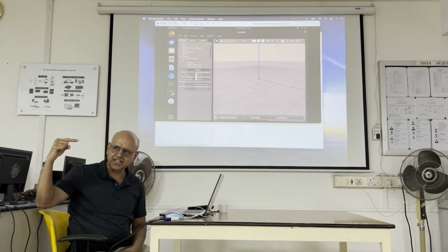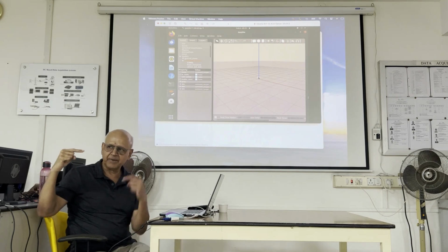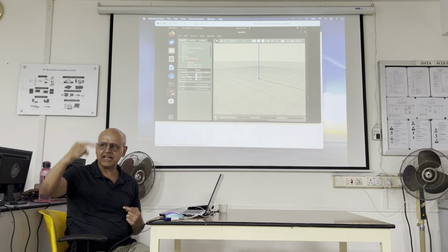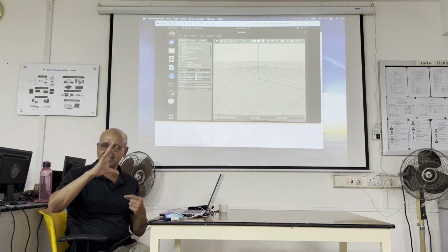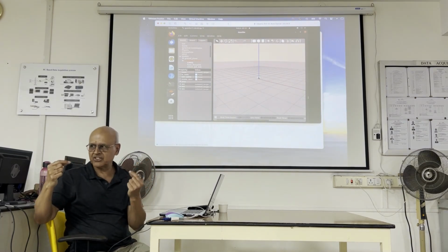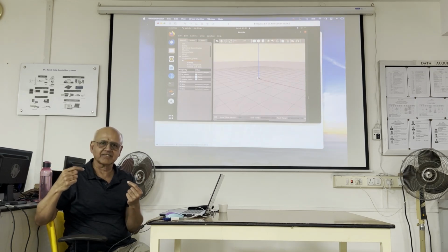And essentially they're shining light from one side and picking it up on the other side. So imagine if you put 1,000 black and white sectors around an optical disc, right? As the wheel spins, you'll get pulses on the other side. So they are not just measuring the full rotation, they are measuring 1,000th of a rotation.